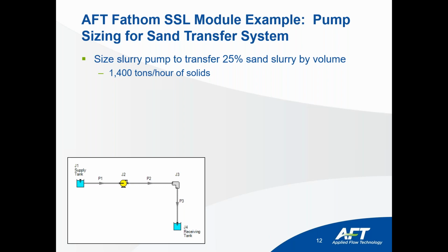When I get into showing you this example here, there's different ways that you can define your flow. You can either define your flow in terms of just the clear fluid itself or the slurry flow rate. The slurry flow rate includes both the liquid and the solids moving together. However, this is a case where I want to specify the flow rate of the particles themselves. So if you're trying to move as many particles or solids as you can, then that might be where you would have a requirement on the solids themselves rather than just the slurry itself.